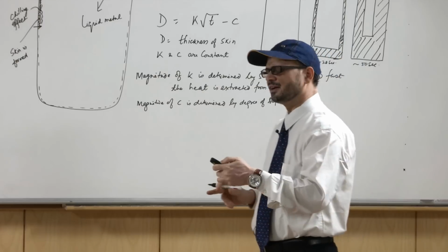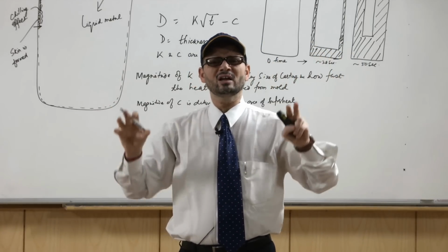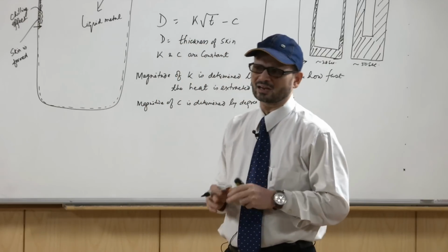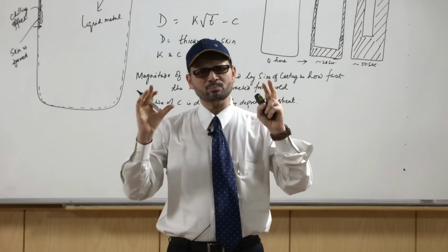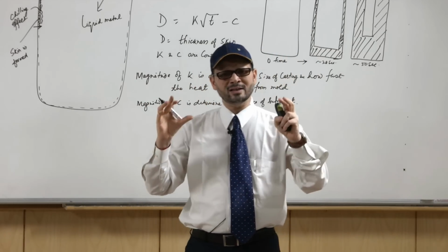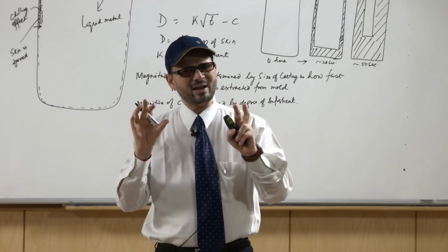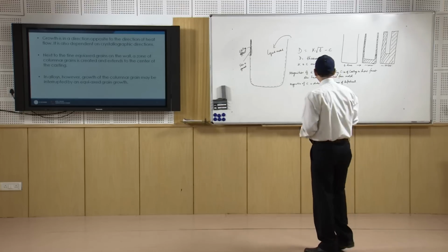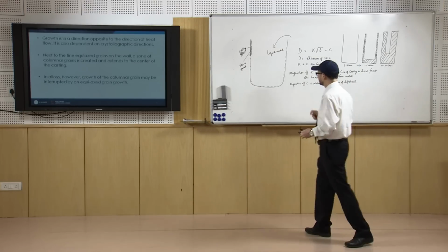That is the difference, and that is why you have more nucleation sites in case of heterogeneous nucleation. Whenever we try to have more nucleation points or more nuclei, then sometimes it is also a common practice to provide heterogeneous nucleating agents. Now, what happens further, that we will see in our next slide.